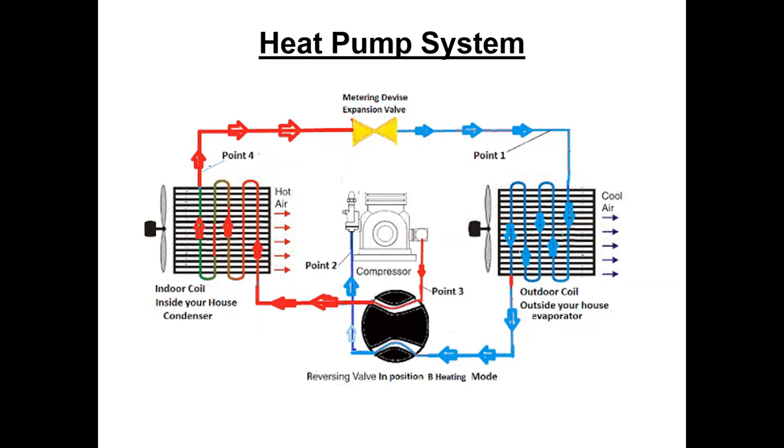So that really cold refrigerant goes through that outdoor coil, and you blow that outdoor air across it at 20, and guess what? You pull heat. You cool down that 20-degree air to 15, and that heat goes into that refrigerant, okay? And so that refrigerant boils away.